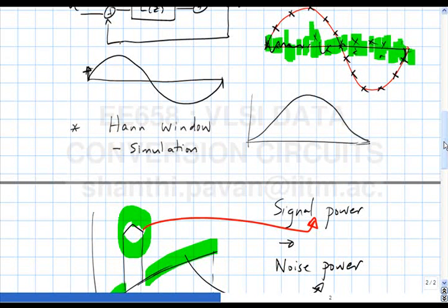But if you have single bit quantizers and low order modulation, let's say you try a second order modulator with a single bit quantizer, you can definitely find input sequences which will cause the output sequence to become periodic. I will not go into the details here. I have set up an assignment to illustrate this point.